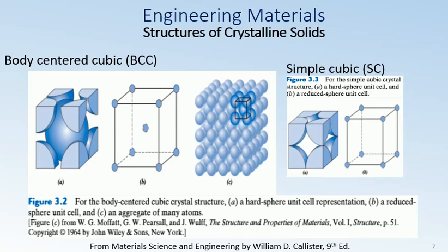structure. As far as we have seen and talked about, for a BCC unit cell, an atom is located at all 8 corners, and one complete atom is at the cube center within the unit cell. Again, center and corner atoms touch one another along cube diagonals, and unit cell edge length a and atomic radius R are related through the relation a = 4R/√3.